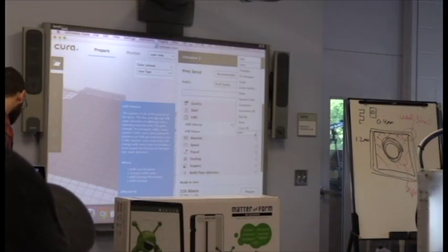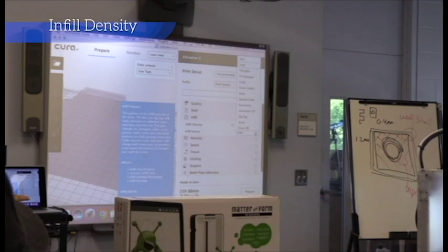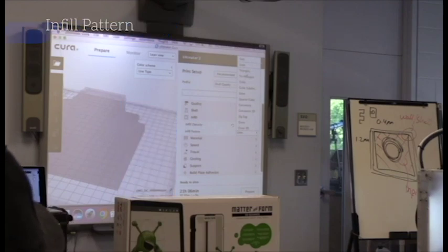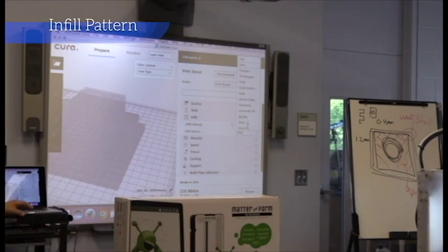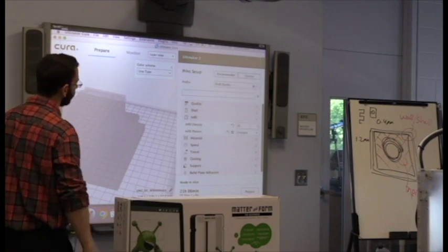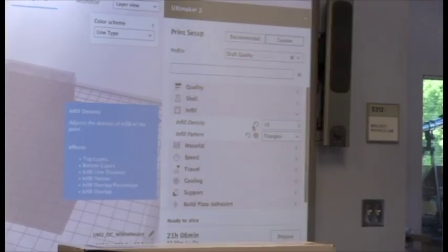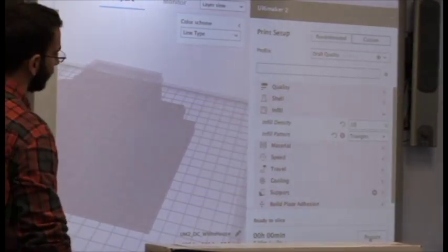Okay, look, infill pattern. And here in this one, look at that. Before they used to have it in the back end of the software, which is where you define what type of infill. And here they have them all for you, right up here. Triangles, trihexagons, cubic, whatever you want. So it tells you what type of infill you want. So if I want to switch to triangles and make this thing maybe 10%, 20%, should be 10%. Okay, and I click on prepare.